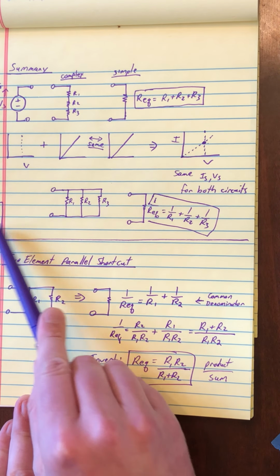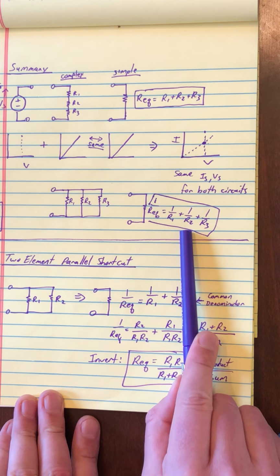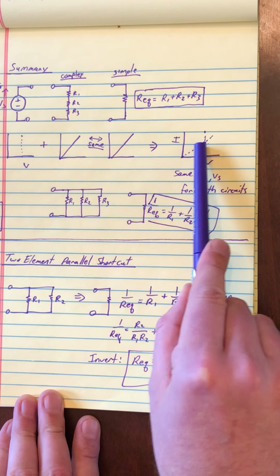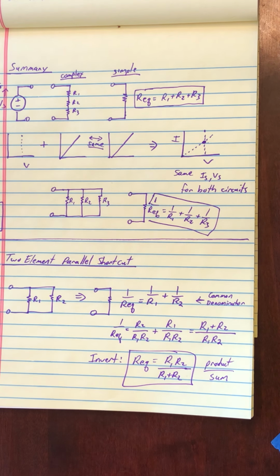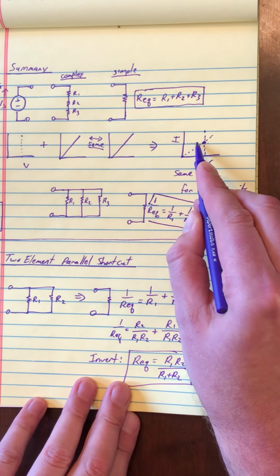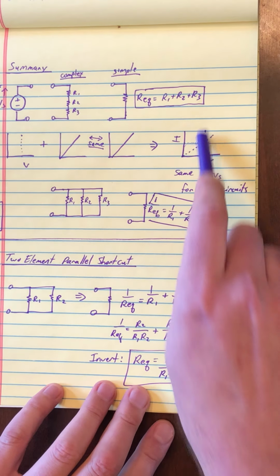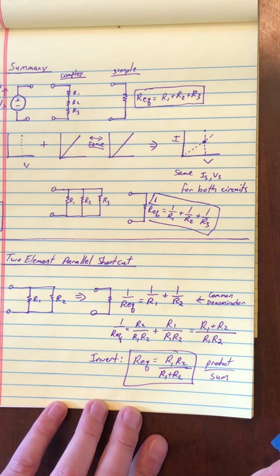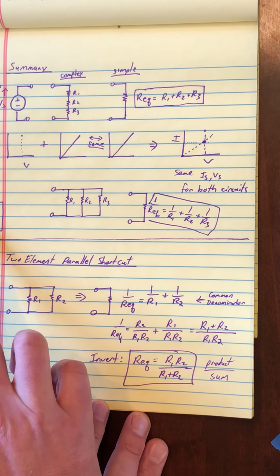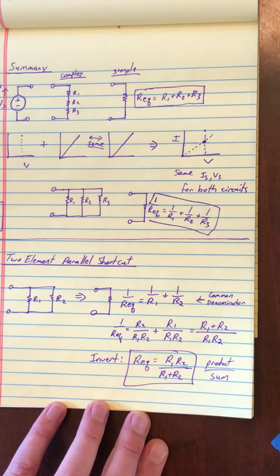In a parallel sense, it's the same thing: a complex network turns into a simple one, with a different way of finding the equivalent resistance. But the application here is nearly identical for finding the current, except that we're using a source voltage for this one too, so you would know that voltage and that IV characteristic when we find the source current. So for parallel, voltages are always equal and currents add, and that is again from KVL and KCL.